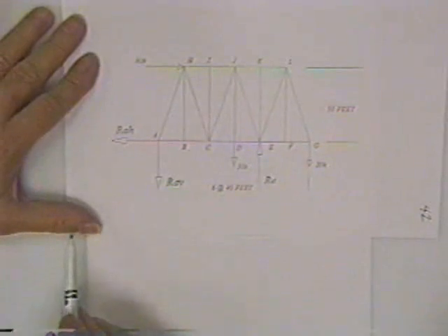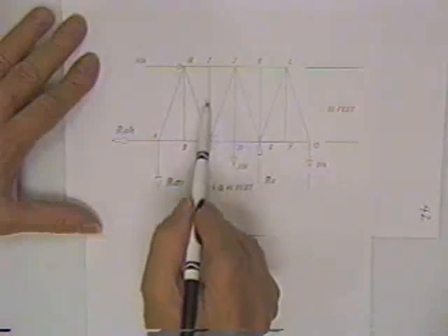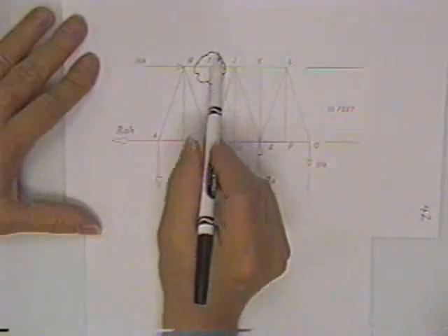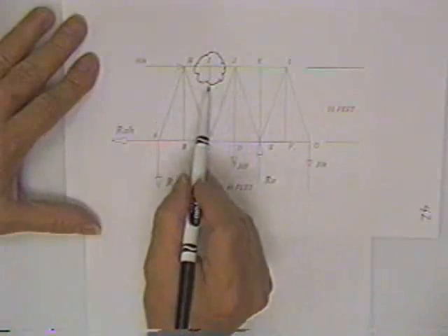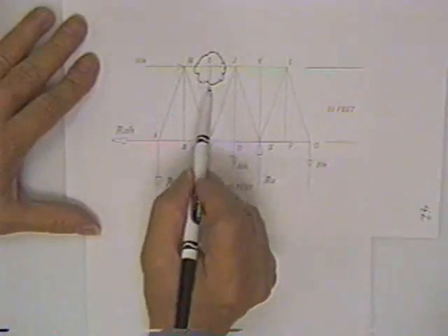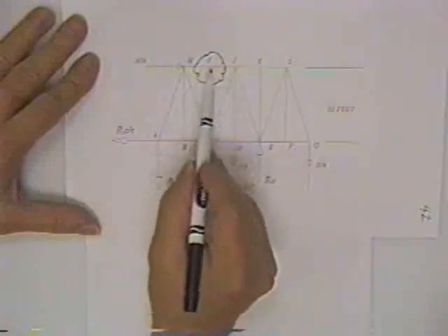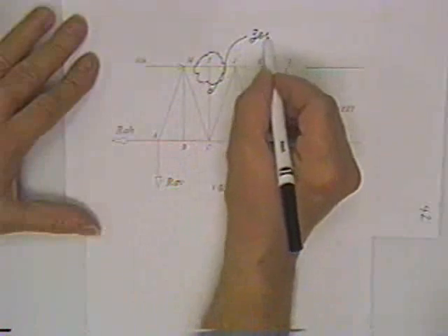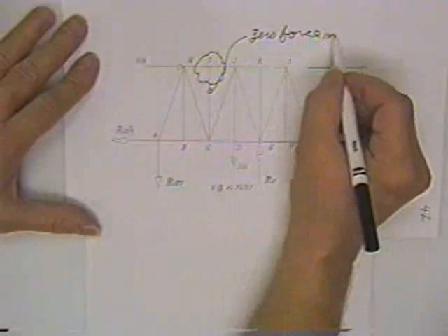Let's say that I have been asked to solve for the force in member IC. If you will notice, you can go ahead and try and solve for it. There's 3 unknowns. Usually you can't. But in this case, since it is perpendicular to a pair of members that are pure horizontal and have no vertical component, that's what they call a zero force member.